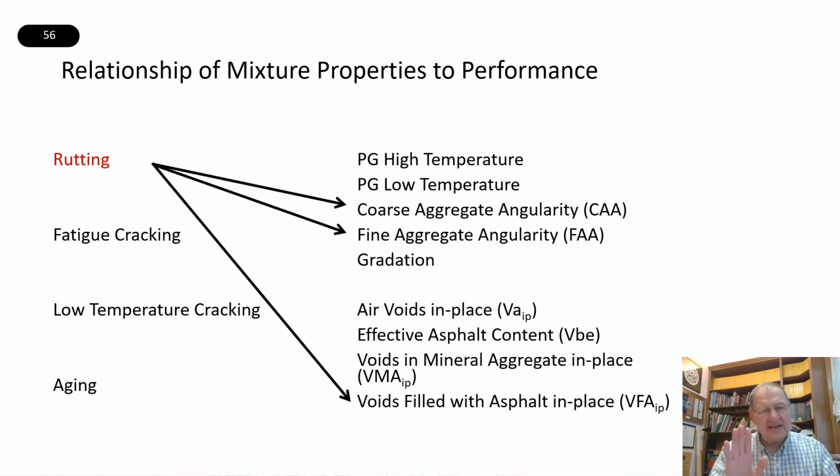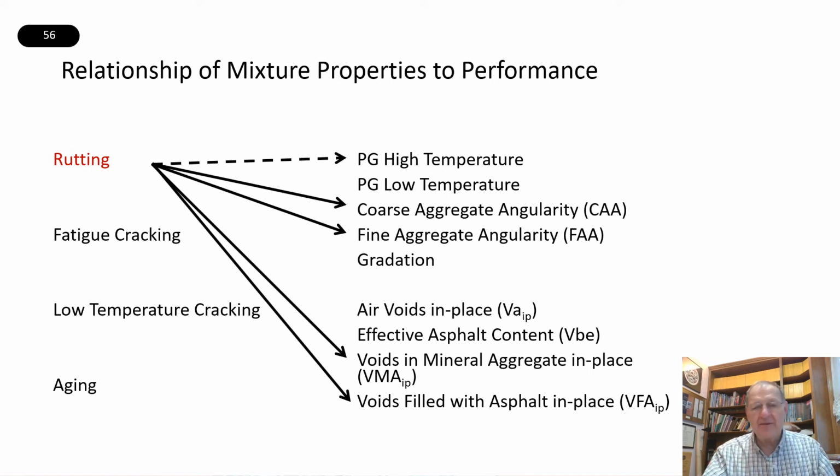Well, it's not exactly the same thing, but it's kind of the same thing on an asphalt pavement. If I completely saturate it with asphalt binder, then the truck tires come and put a load down and take it off, and then another truck tire comes and puts a load down. Now, it doesn't disintegrate the skeletal strength of the asphalt pavement as severely and as quickly as it does at the beach, but it will, and that can cause the rutting to take place. And that's partly controlled by the VMA.